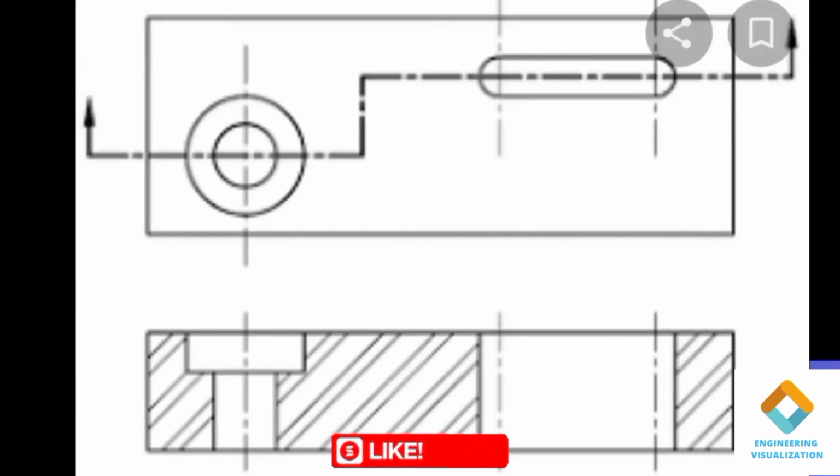Offset sectional view. An offset sectional view is generated by offsetting, that is bending the cutting plane, to show features that are not in a straight line. So this is what we call an offset sectional view of a solid.